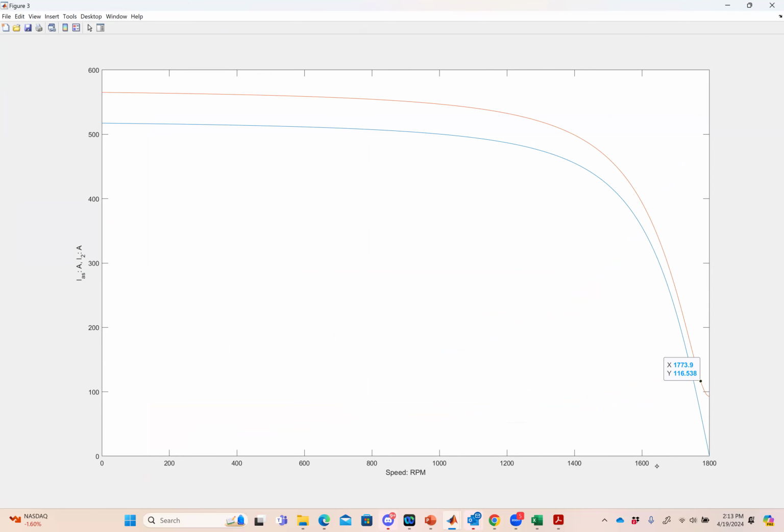So I'd have to have some sort of protection here. You have a circuit breaker that might pick that up, right? If I had a really large motor, there might be a relay measuring it that would actually trip the circuit breaker or something like that. But I often care about those conditions because if I've got a motor that's really big, I would worry about what happens during those conditions, okay? All right, so that's the basics of how the induction motor works.